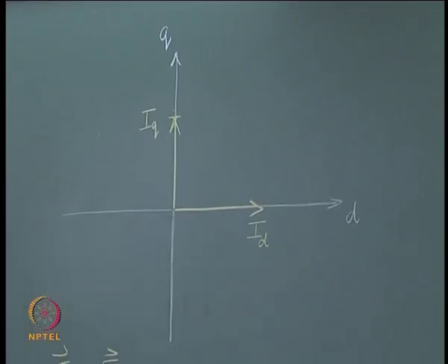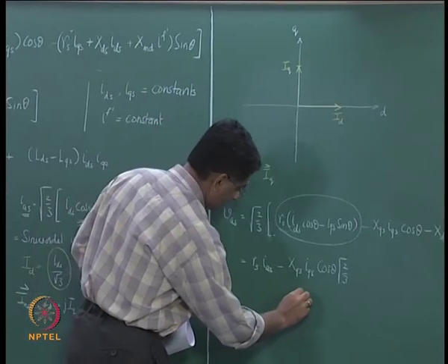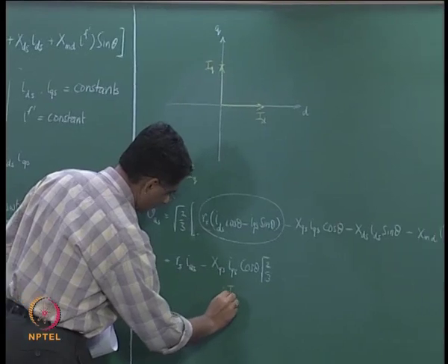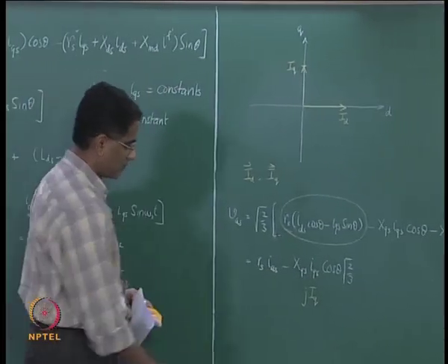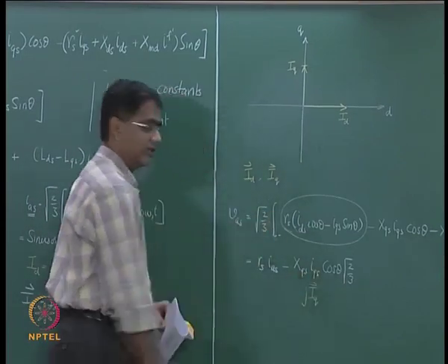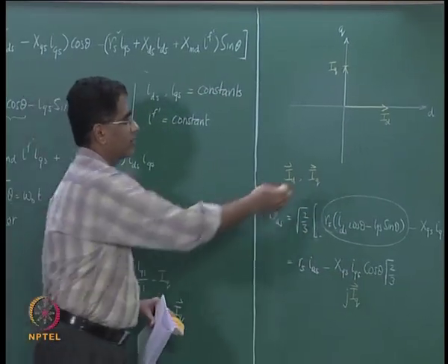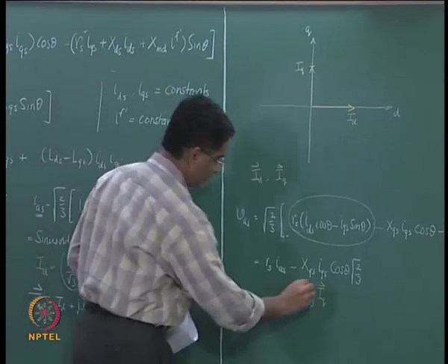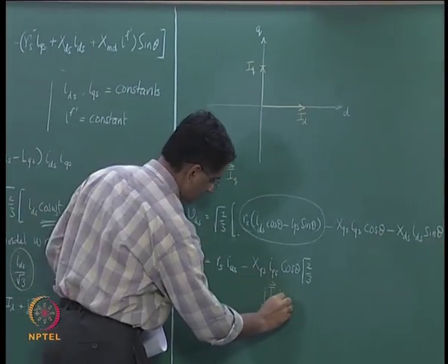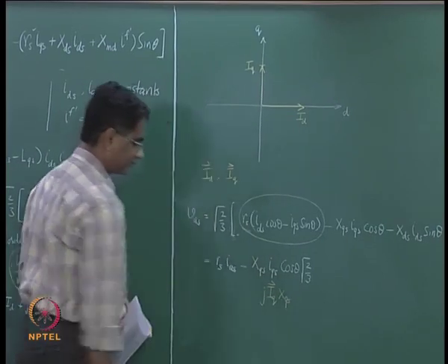A rotation of the Q phasor by 90 degrees can then be written as J times the IQ phasor, because the Q axis phasor is rotated by 90 degrees, and this is then XQS.